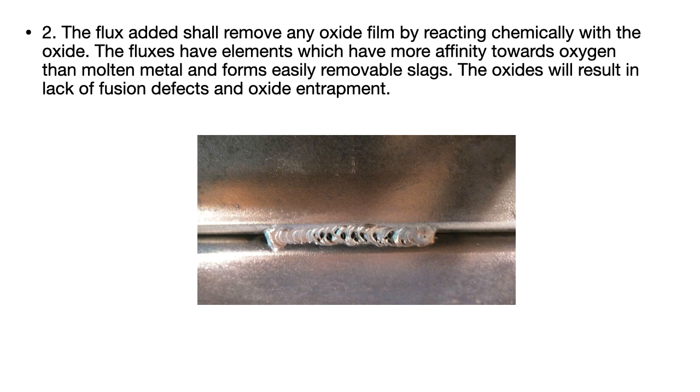Say, for example, right from the manufacturing of steels, steps are taken to remove the oxygen content, or reduce the oxygen content to a bare minimum. During steel production, this particular process is known as the killing process. If you have gone through any material certificate or test certificate of a steel, you can see elements like aluminum, manganese, silicon, etc. Or you could have read that these are killed steels or semi-killed steels.